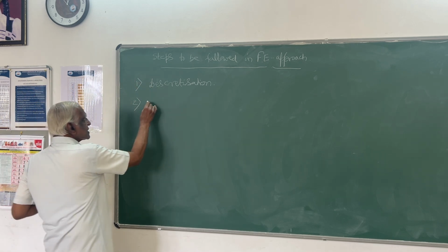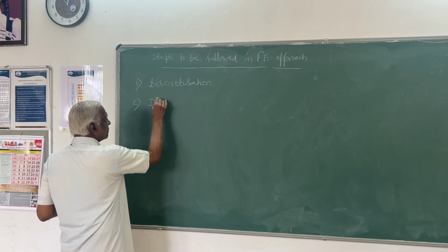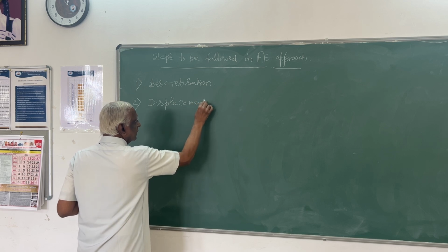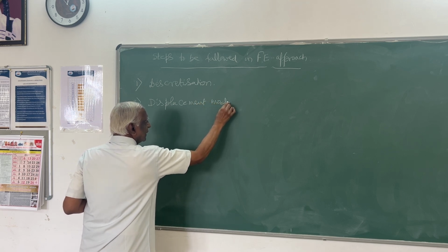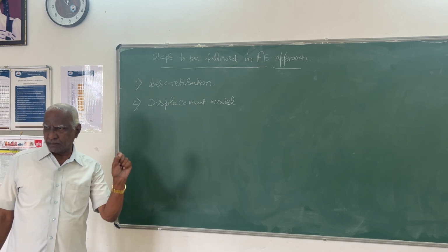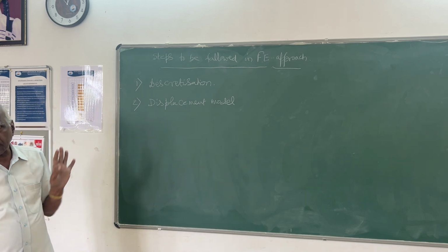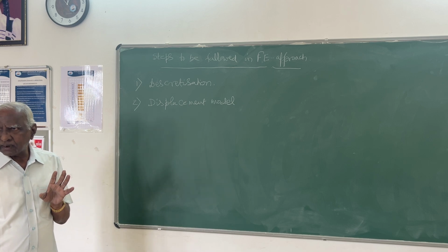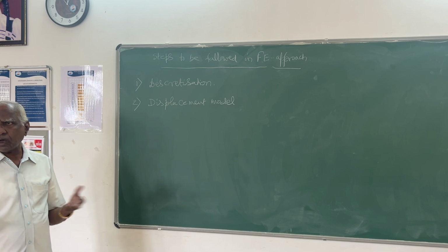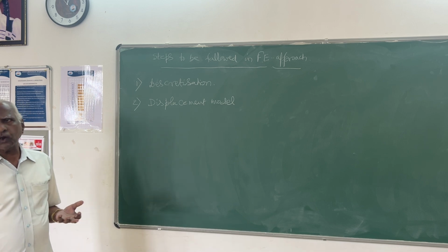The next step is the displacement model. You have to select a suitable variable in the problem. Usually in our structural mechanics problems, the variable will be the displacement, either linear displacement or angular displacement.